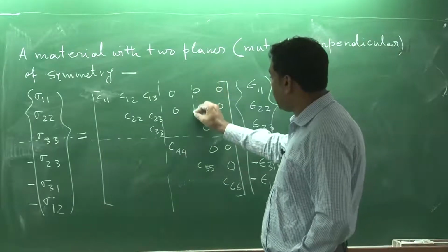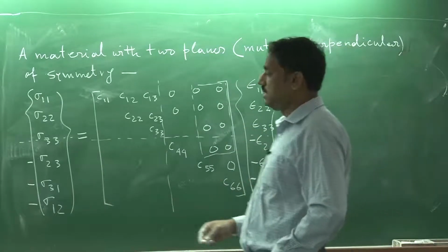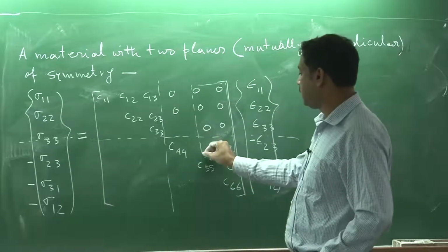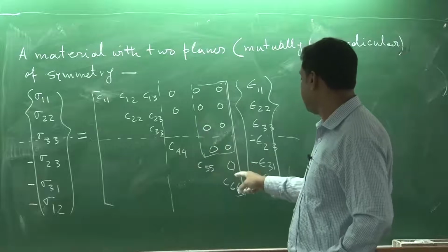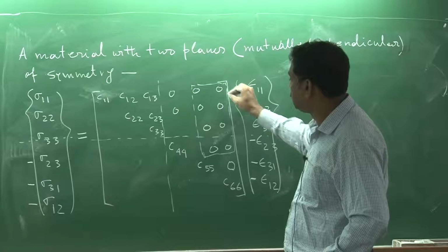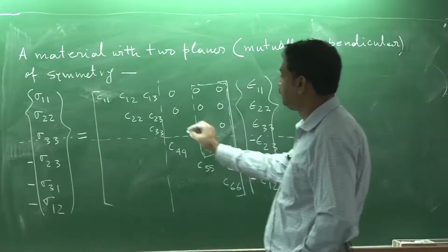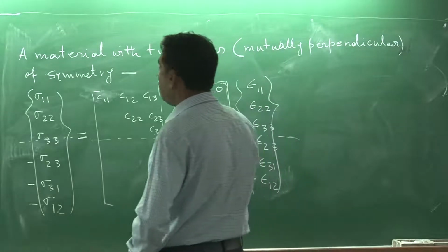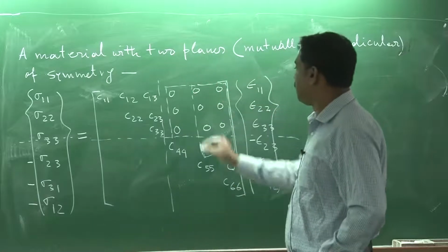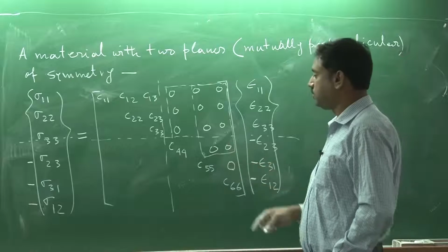So earlier I had this block 0 for monoclinic, but now in addition to that, this is also being 0. So then basically I need to have this being 0, okay, this is 0, okay, you understand that. And in addition to that, I also have this block 0, right, because all three are 0. So these 3, these 3, these 3 are 0 and also these 2 are 0.